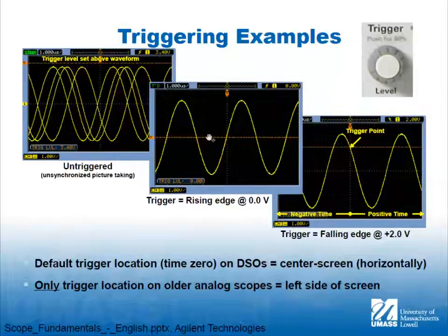So usually you do something more like this, where the trigger point is in the middle of the signal, and that way it doesn't jump up and down. If it's amplitude modulated, you just see the motion up here and down here. But it depends on what you're doing, and the voltage isn't important to us tonight. The time is, and that's what we're trying to get to.